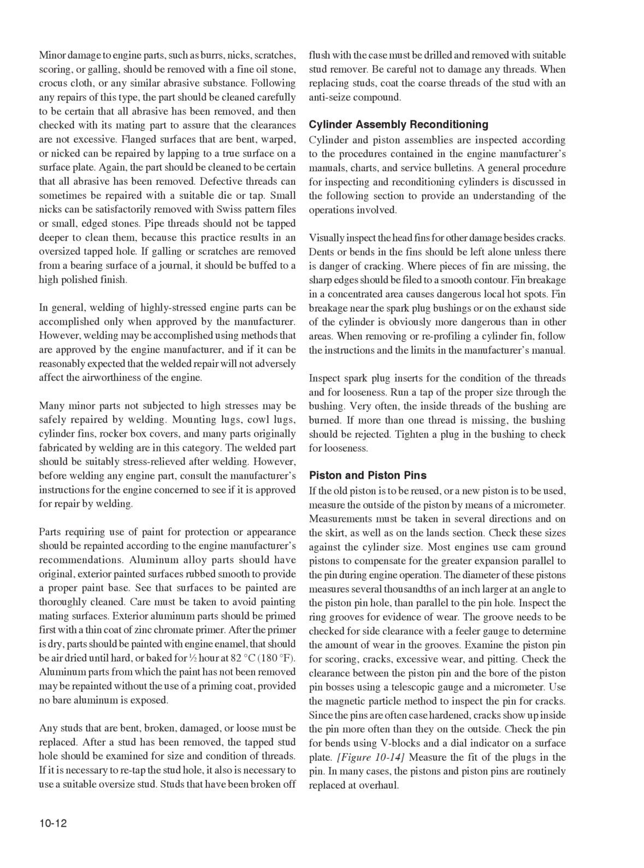Studs that have been broken off flush with the case must be drilled and removed with a suitable stud remover. Be careful not to damage any threads. When replacing studs, coat the coarse threads of the stud with an anti-seize compound.